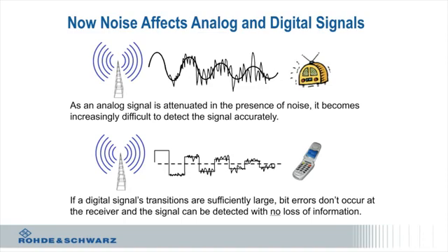It's reduced in amplitude, it becomes more and more difficult to detect that signal relative to the noise around it. So you'll see an analog used to have that hissing noise, but digital receivers actually have coding put into the signal, so it actually has redundancy built in. So typically you won't have that hissing noise, but you'll have a more steep break-off where you will start having blocks of data where there's no sound at all, for example, on a satellite radio, or you'll just lose your signal altogether.